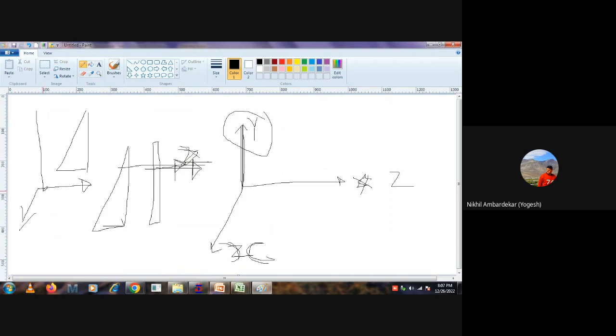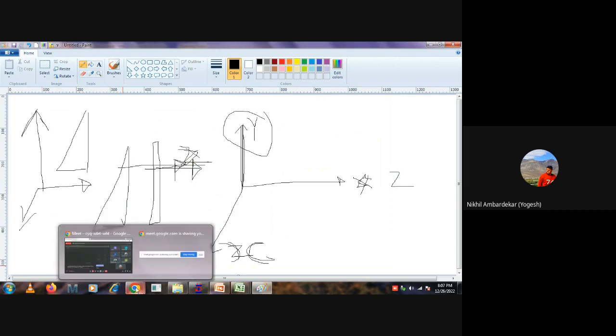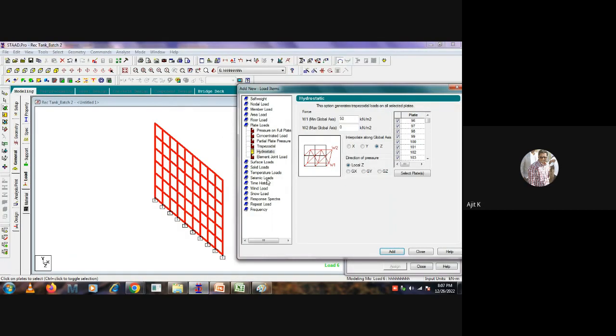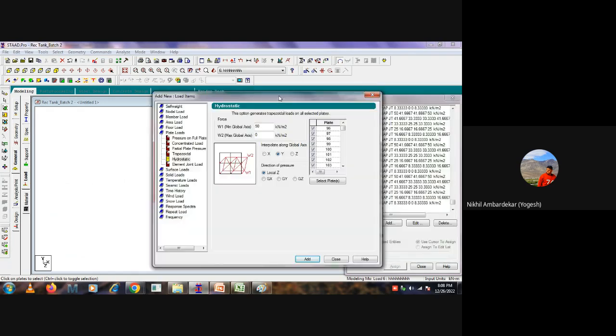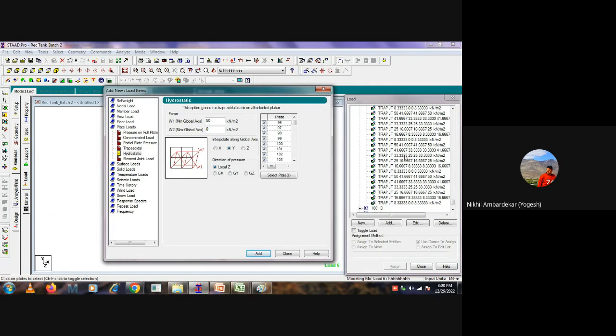provide another 90-degree angle. So that is always Y. With respect to Y, global Y. Because this is Z and this is global Y. In that case only this triangular can form, correct? So if I just click on Y, you can see, now it is added.